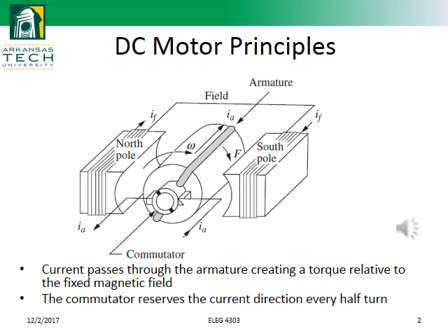When the armature is in the 90 degrees position, we need to have a device called a commutator. The commutator's job is to reverse the flow of the circuit, thereby continuing rotation of the armature.